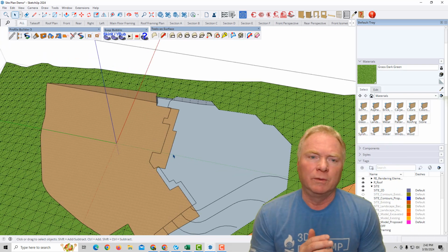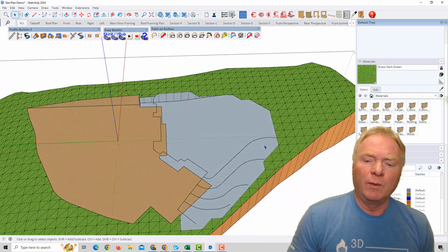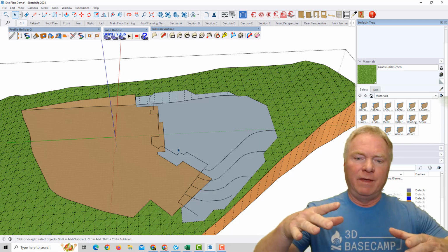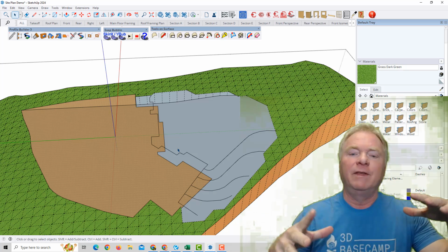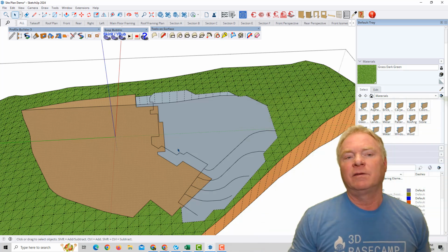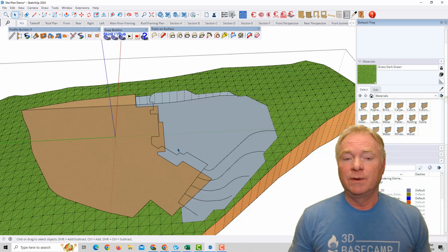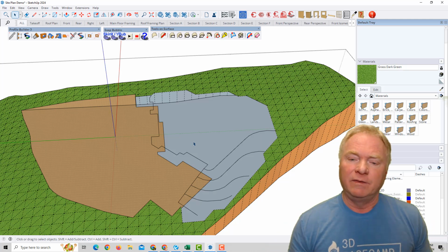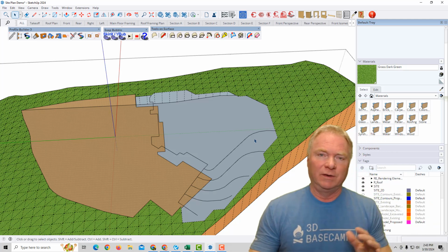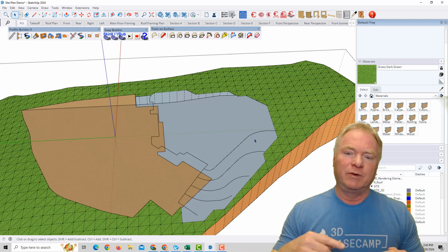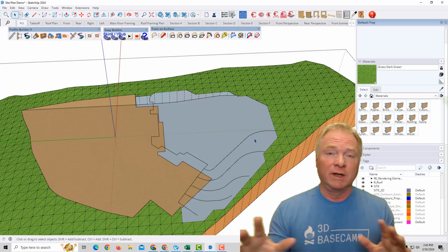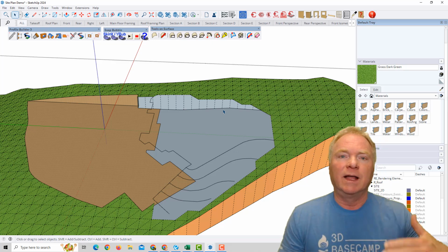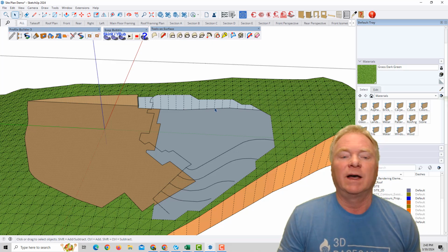All right, here's where I'm going to use Soapskin Bubble. What I want to do is select edges that close a loop that I can then change the contour to fit the contour in there. I could do the same thing and select those things and go to Sandbox tools, and it would create that mesh, but it's going to add a lot of geometry inside of these curves. I could show you, but it's a mess. You would get all this extra geometry that you would then have to edit and delete. If you've ever done this, you'll know exactly what I'm talking about. So Soapskin Bubble is just cleaner, and it's less intense on the model size.